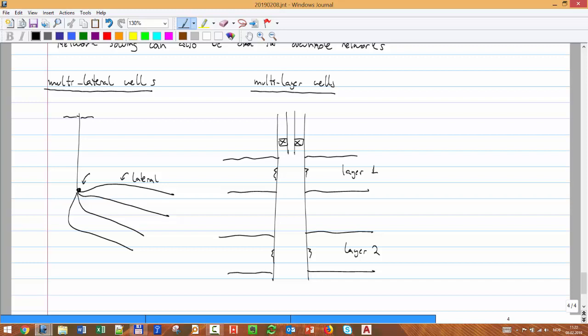Sometimes we can have a very big layer, a very big volume, but with low productivity, so that we have to produce slowly. And then we have a very small layer, but it's very productive. So what happens after time is that one depletes quicker than the other. This pressure goes down quicker than the big layer.